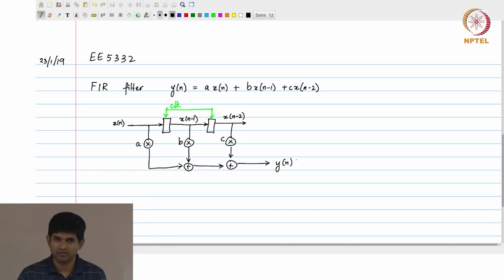Okay, and what determines that? What would it be that determines the rate at which this architecture can process data, assuming that somehow I can provide my input samples fast enough? Remember, we had this discussion earlier where we said that normal signal processing algorithms have this property that very often their sampling rates are set by some physical constraints. For example, there's no point in sampling voice at more than, let's say, 44 kilohertz or something like that, even music, right?